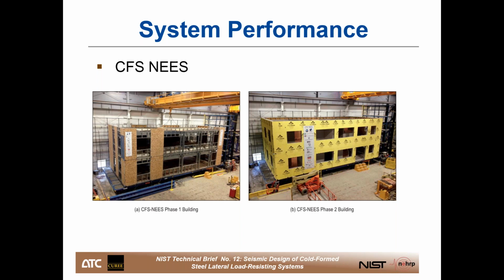Then we deconstructed that system and rebuilt it, tested it to make sure it was the same. So we ran what was called white noise tests to make sure it was behaving the same as the original phase 1 structure. And then we started adding stuff to the building and doing additional tests. So the additional tests were completed after addition, for example, of full exterior OSB, interior gypsum board on perimeter walls, interior partitions, and finally everything through the exterior finishes, which is kind of what you see on the picture on the right.